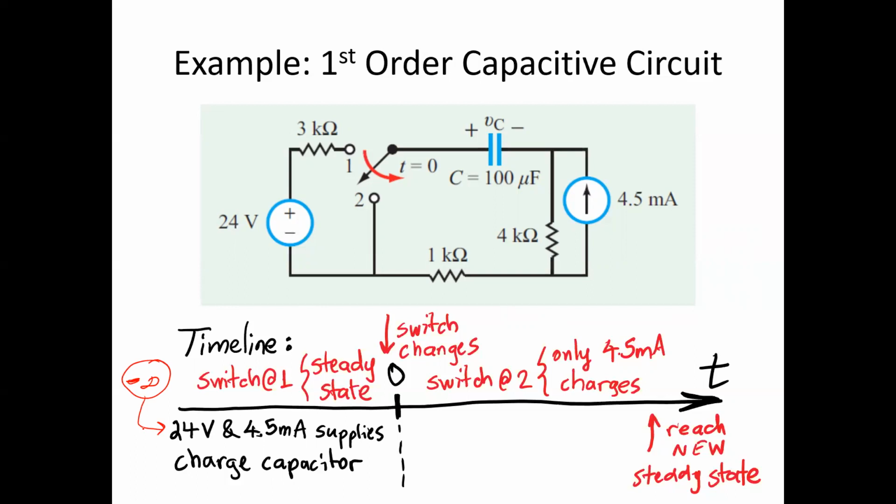Once it's done completely charging, the capacitor enters a condition of steady state. What this means is that we can use the principles of the behavior of the capacitor at steady state to figure out what exactly the capacitor voltage would be. We'll do that shortly on the next slide. But let's just stay where we are. We have our capacitor completely charged. What this means is that the capacitor will no longer be passing any current,